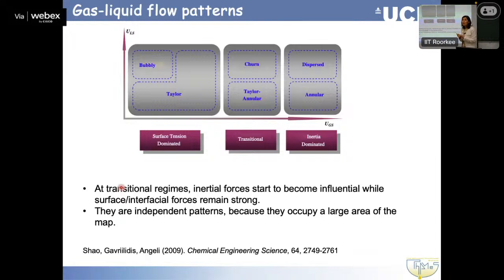So it's basically the volumetric flow rate of this phase divided by the whole area of the channel. Yeah, so this is superficial. So it's not the actual velocity. If we knew the actual area that our phase occupies and we divided the flow rate by that particular area, then we would have the actual velocity. Very often in multi-phase systems, it's very difficult to know in situ what is the actual area occupied by a phase. And that's why superficial velocities are used. Superficial velocity is basically a flow rate, not non-dimensionalized, but with a reference to the area of the channel.